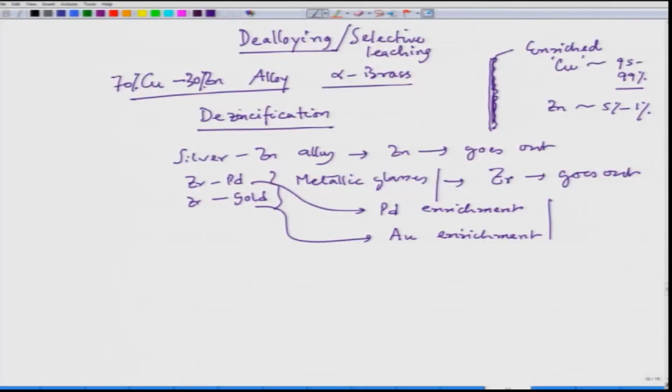This copper region is loosely stuck to the inner surface, and it is also porous. So, after some time it might crack, that pipe might break or leak. So, from the point of holding the structure, this is not good.